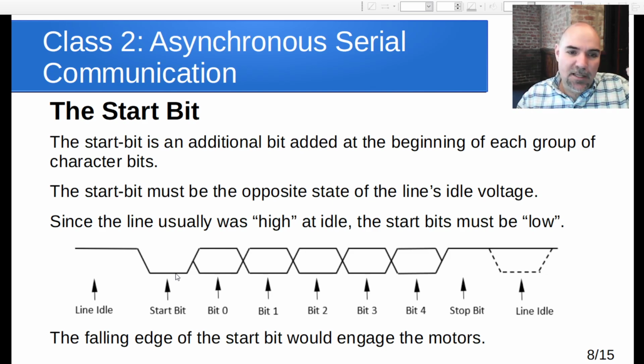If the line is high, you could have a little light or a needle, or maybe you put a meter on that, whatever. But if it's in the high state, you can immediately tell that we're connected. There's just nothing coming through. Whereas if it idled low and the line got broken, you'd say, well, there's no message coming in, but it could be that the line is broken.